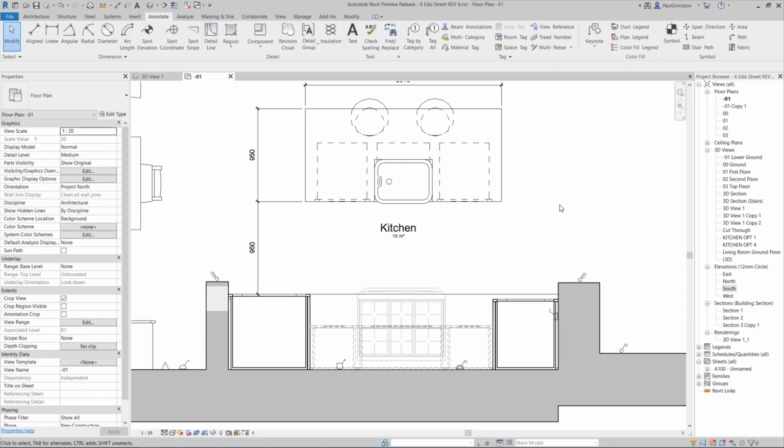But what's also very useful is that we're now able to get this information into schedules and also display it on tags itself. So this doesn't apply to all objects in Revit. It's mainly around the MEP objects, the mechanical equipment, lighting, communication, electrical fixtures, etc. But from an architectural design interiors point of view, it also applies to furniture and casework and generic models and specialty equipment as well.